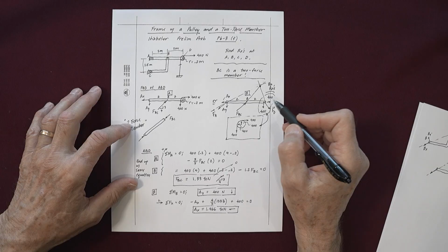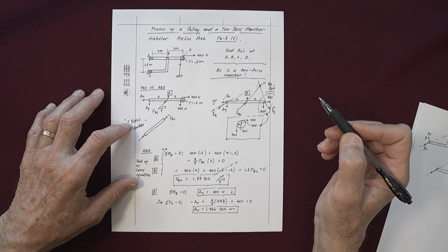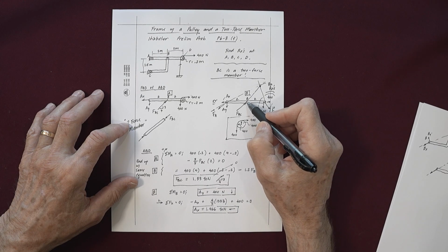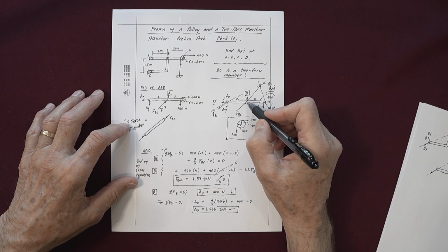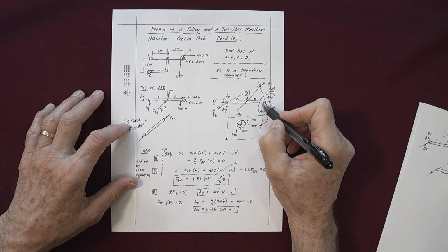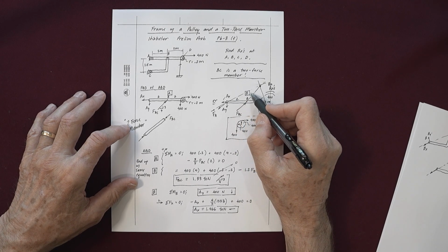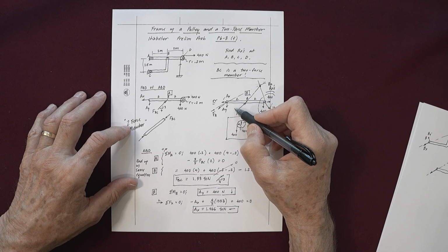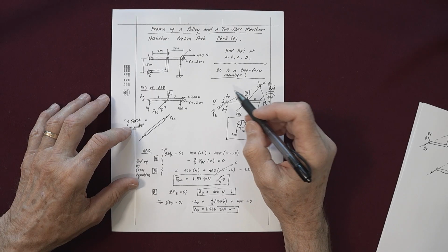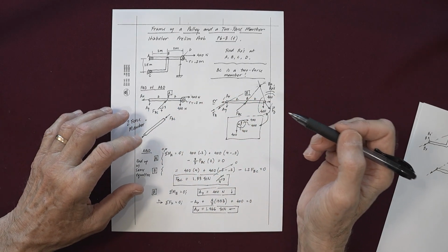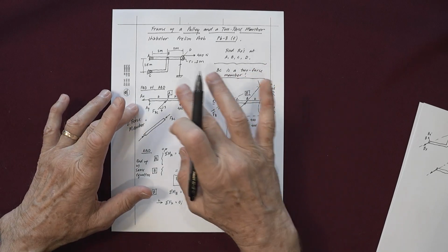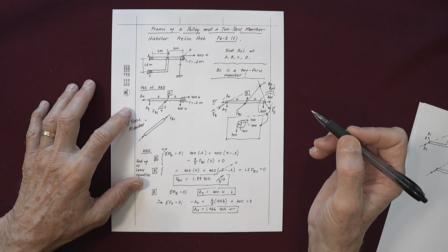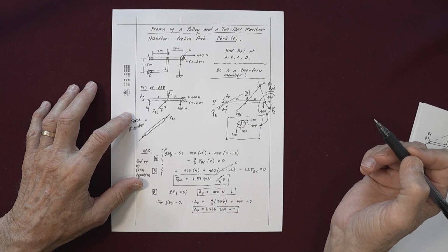So in this particular problem, before you leap into drawing AY vertically, what you can do is think about putting a pivot at B and taking moments about B. If you take moments about B, you know that this 400 is acting down, which is going to make this guy pivot clockwise around B. So AY actually has to act down to keep this guy in equilibrium. And so I realized that when I was working this problem. So stop and as you think about the reactions at each of these, stop and think about what possibly is the correct direction. So AY actually should be down.